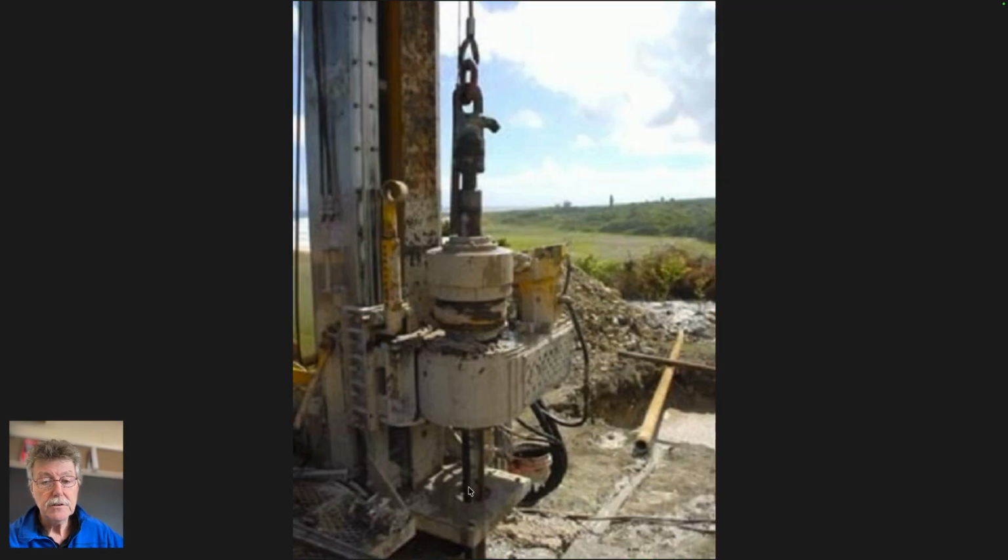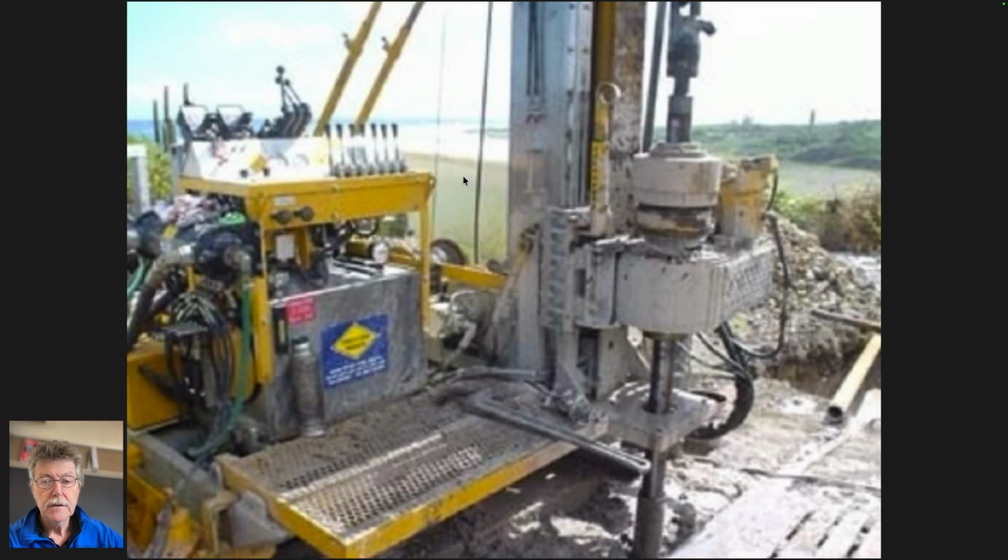So this is a turntable. This is a drill pipe, hollow pipe that goes down into the ground. This is a turntable which provides the motive power to turn with the drilling shoe down the hole somewhere. This can be pulled down into the ground so you can push against the bit at the bottom of the hole. And this is a wire line up into the top of the mast, which is attached to drill steel here with a swivel attached to it, which will pull the drill steel out and put it up the mast. So that's exactly it here. This is a casing that goes into the ground.